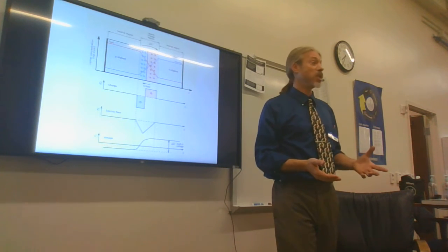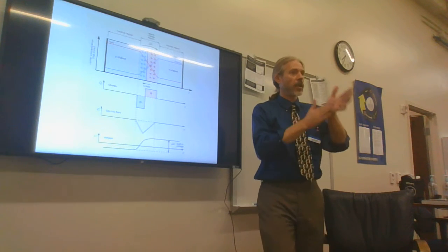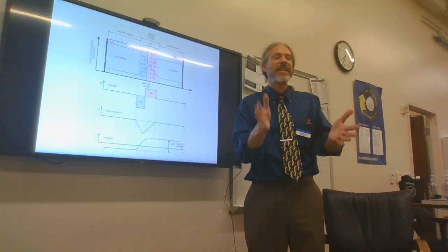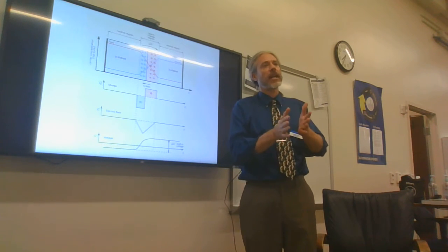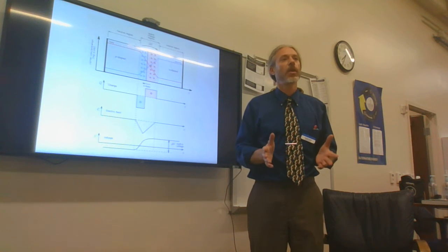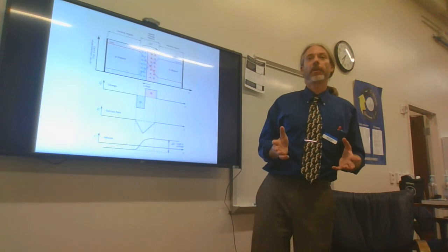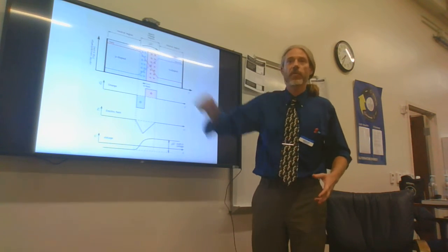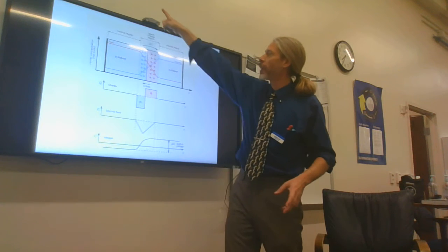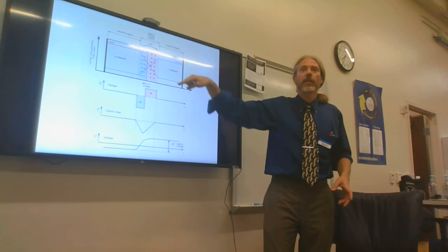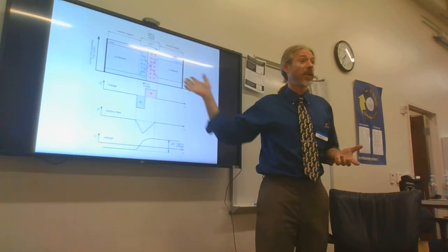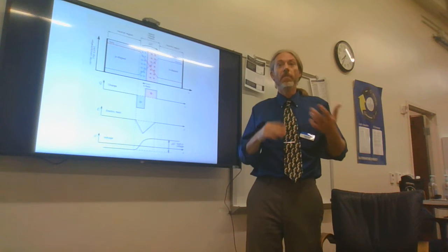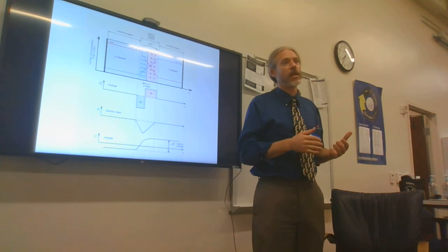That's called a diode. A diode is an electrical device that will only allow electrons to flow in one direction. That p-n junction has created a diode to where the electrons want out of the top. In fact, there's pressure for them to get out of the top, but there's no path for them to get through this middle region. If we provide them a path around to the back, they will go through the load, assuming they can overcome that resistance, and they'll rejoin. All right. The power to motivate them to do that comes from the solar radiation.